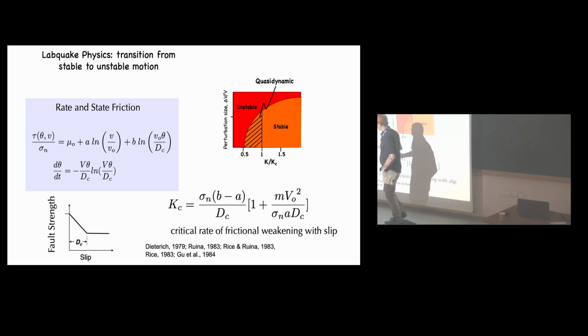It is a statement about the idea that the shear stress at sliding is a function of some state variable and velocity. It's only these two things in this particular case. It could be a function of other things, but the normal way you write down rate-state friction is that friction is a function of these variables. If I just divide the shear stress by the normal stress, I get the coefficient of friction, and I get something that looks like that.